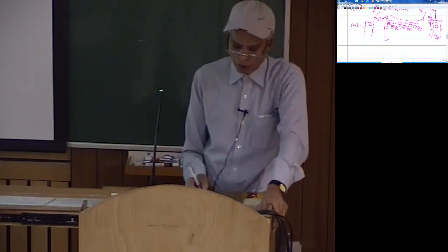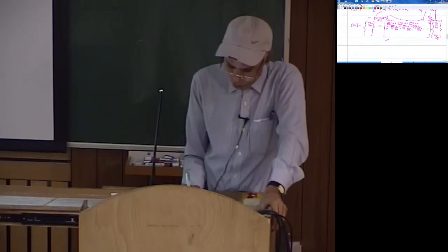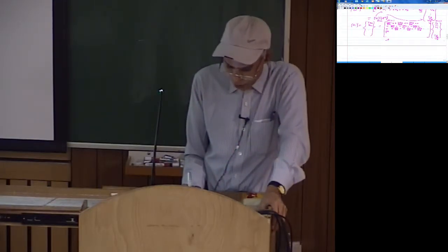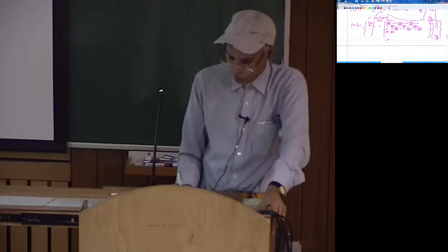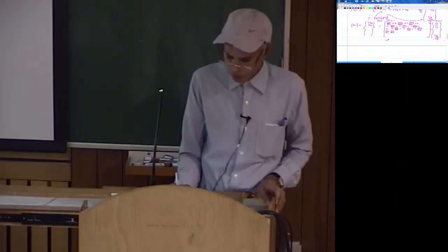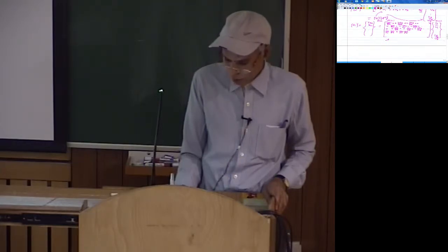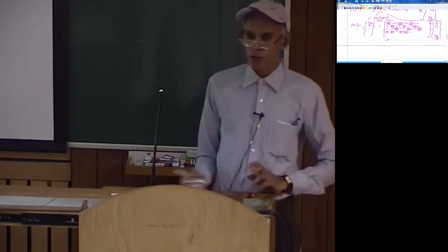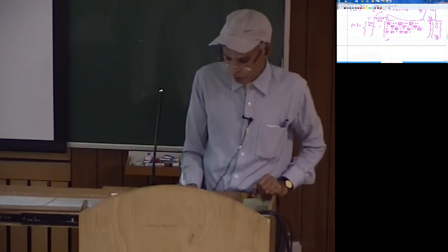And then when you look at the fourth one, say gamma xy, which is del u by del y plus del v by del x, you will have del N1 by del y here and then del N1 by del x. So this will give you del N1 by del y into u1 plus del N1 by del x into v1, so that is coming from del v by del x. In the same way this will then be 0 and then del N2 by del y and del N2 by del x and 0 and so on. So like that you can write for the remaining 2 more components of strains in a similar manner.